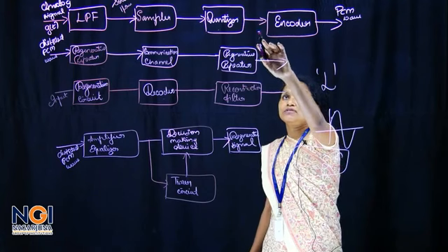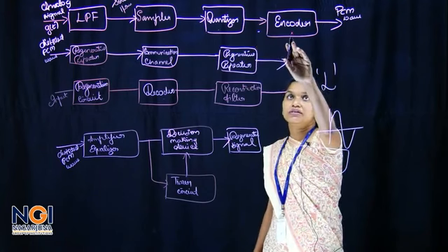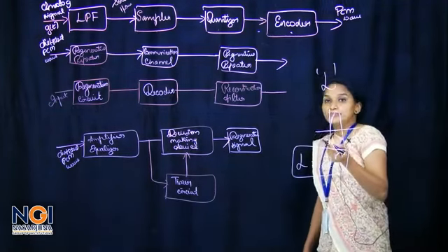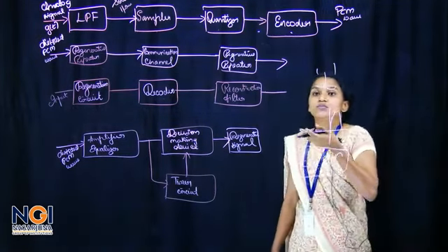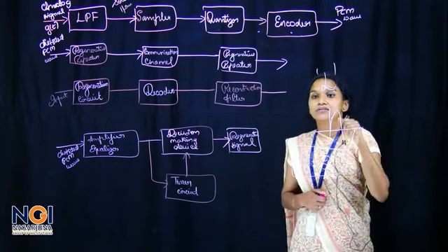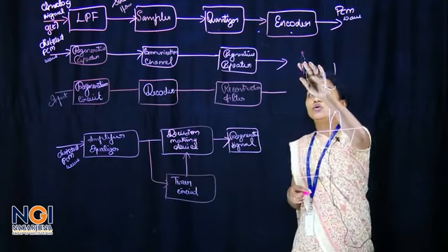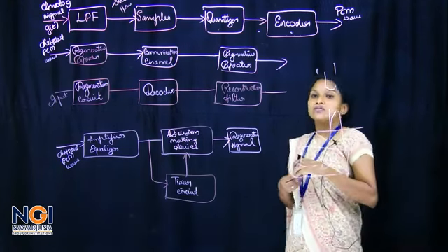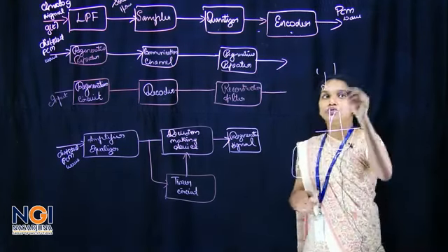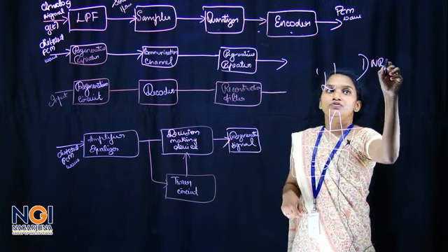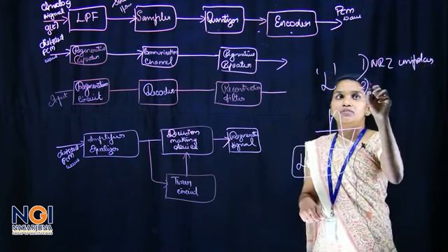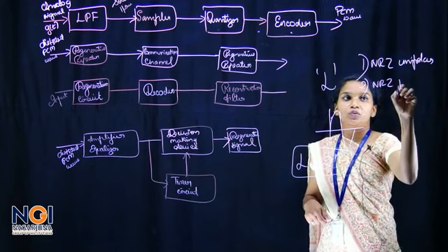When the various binary levels are encoded in the encoder, the binary digits are transformed into an electrical waveform. In the encoder, the binary digits are represented as an electrical waveform in two forms: non-return to 0 unipolar waveform and non-return to 0 polar waveform.